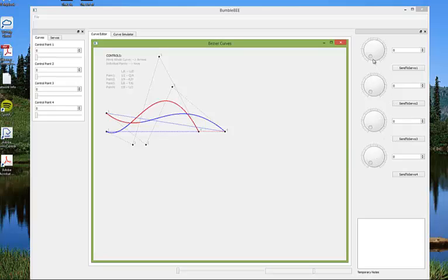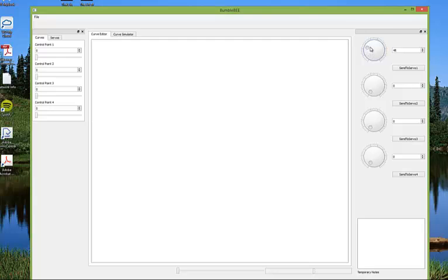So basically, in the manual mode, you actually click and you can rotate the servo to change the rotation, or you can manually edit it in here, and then once you have it at the degree that you want, you hit send to servo, and I don't know if you can actually hear that or not, but the servo rotated.